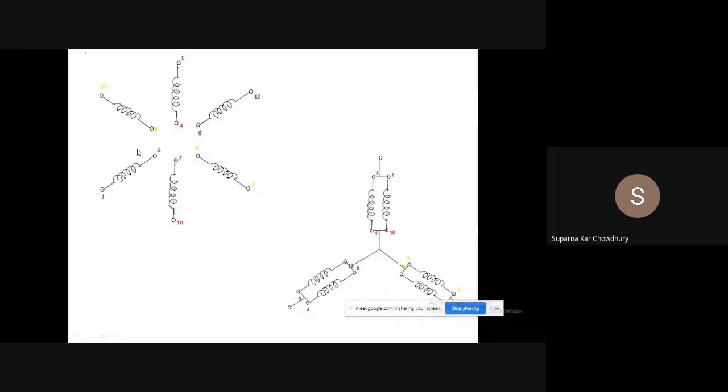Now as you have determined the winding position of the transformer, similarly this also can be done. What is the position of the windings and so on. That is simply what we can do: if we short these terminals and the alternator is driven by the DC motor at a particular constant speed, and if we apply DC excitation to the alternator field, then EMFs will be induced in all the windings. Then the EMFs can be measured.